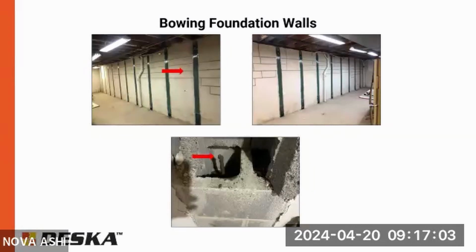That's another option. Obviously, you would have preferred to do that when the foundation was being built. To do that after the fact is much more time-consuming and expensive. Also, you don't know what kind of debris is in the wall from when they built the foundation. If there's all kinds of trash and insulation or who knows what in the wall, you may not be able to get the rebar where you need it to go, and the same with the concrete. So it's a little bit of a guessing game. So we generally don't recommend the shear pins.